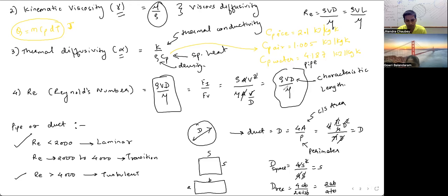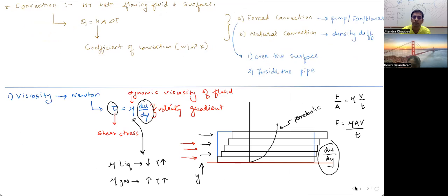Can I just run through with you quickly? The steps for forced convection are to find the Reynolds number first, and then the Prandtl number, then the Nusselt number, and then the coefficient h, right? Oh yes, correct, very good. But before the Reynolds number, you must have the values like density, dynamic viscosity, velocity. If not, you have to find them. There are some basic formulas you must know.